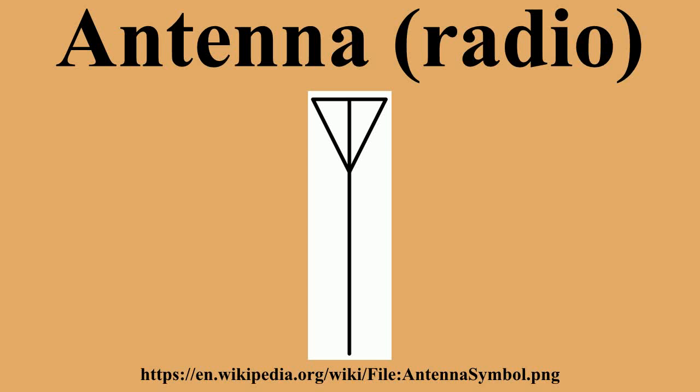An antenna lead-in is the transmission line which connects the antenna to a transmitter or a receiver. The antenna feed may refer to all components connecting the antenna to the transmitter or receiver, such as an impedance matching network in addition to the transmission line. In a so-called aperture antenna, such as a horn or parabolic dish, the feed may also refer to a basic antenna inside the entire system, which could be considered the one active element in that antenna system. A microwave antenna may also be fed directly from a waveguide in place of a transmission line.